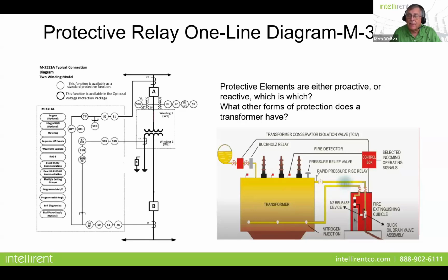And that is this: if your differential relay trips at any given point in time, and it's not a false trip or a nuisance trip or something that came from a bad setting, that means that the fault is already present within the transformer, within the protective zone of that protective element. The damage is done. It's just there to make sure that no further damage is done or any catastrophic damage occurs as well.